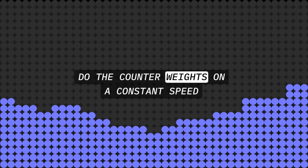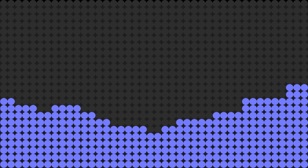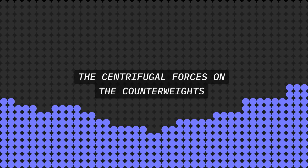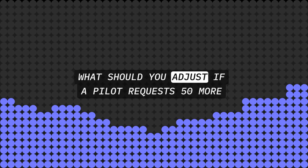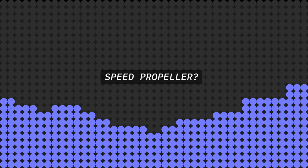Do the counterweights on a constant speed propeller increase or decrease the blade angle? The centrifugal forces on the counterweights increase the pitch of the blades. What should you adjust if a pilot requests 50 more RPM on an aircraft equipped with a constant speed propeller?